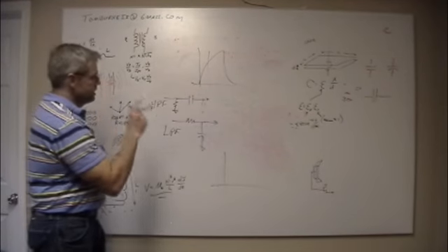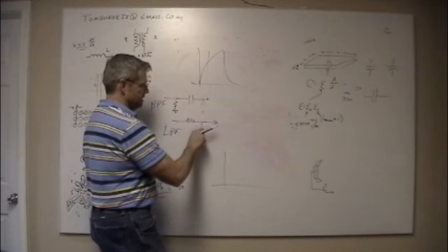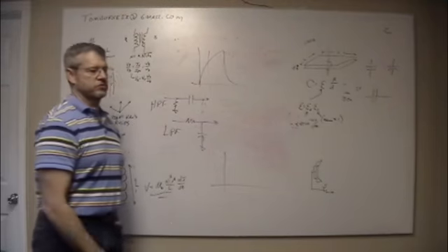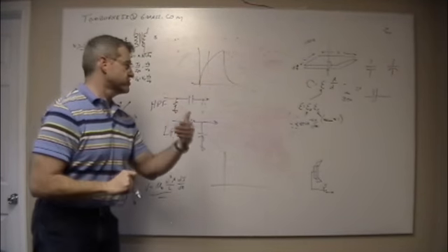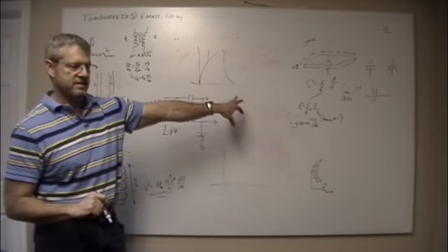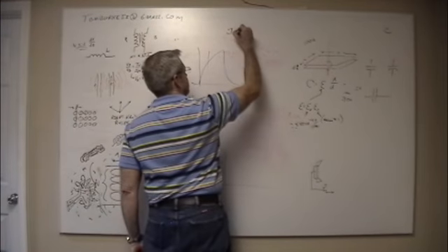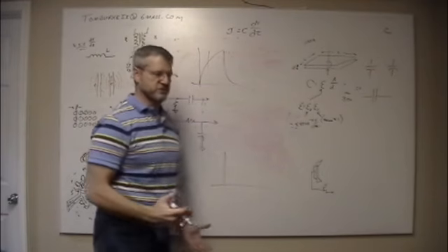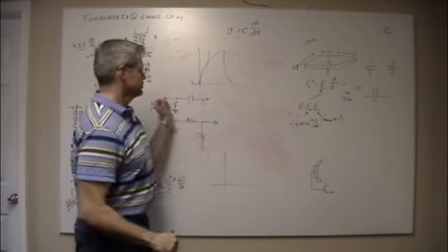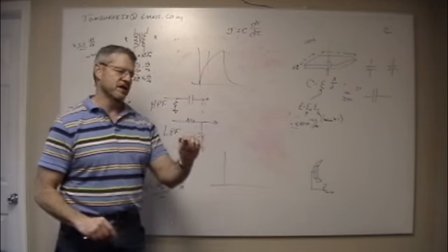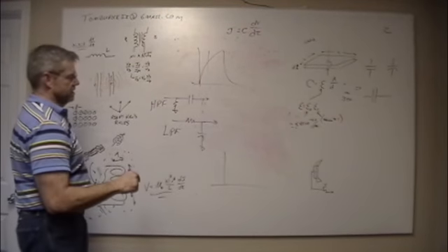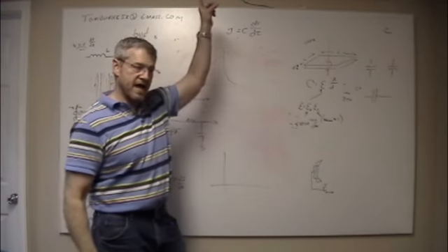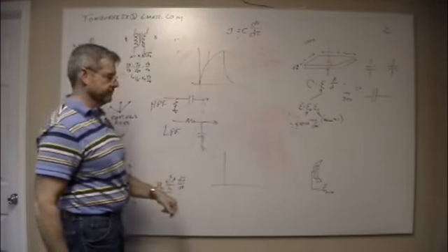I'm going to see here, remember we talked about how low frequencies this blocks a low frequency, very slow change. The change is so slow when you look at that I equals C dV/dt. When you look at that, the dV/dt is practically zero. It's moving really slow, so current's zero. There's a little bit there, but not much. But on the other hand, if I'm moving really fast, like we showed here, current goes really high, right?